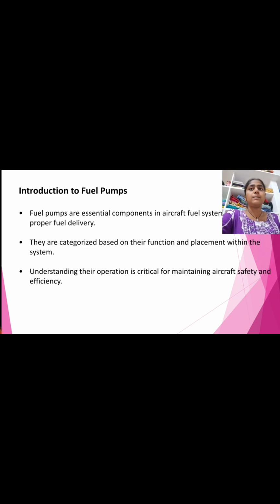First, coming to boost pumps. Boost pumps are typically located inside or near the fuel tanks and are primarily used to supply fuel at positive pressure to the engine driven pump. Their main function is to prevent vapor formation and cavitation in the fuel lines, especially at high altitudes where pressure is low. Boost pumps ensure a steady and uninterrupted flow of fuel by maintaining adequate pressure in the system.